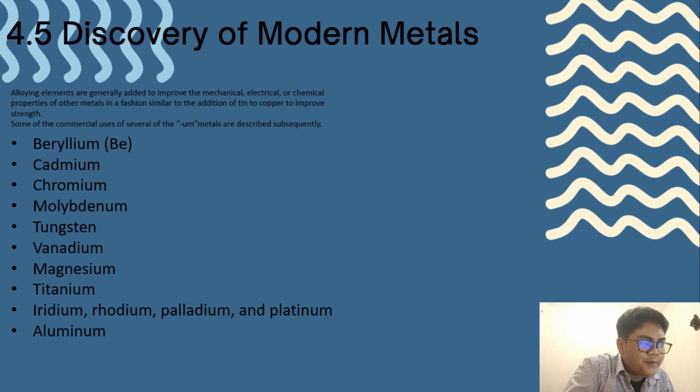Zinc addition to copper produces brasses. The copper beryllium alloys contain only a small amount of beryllium, approximately only 2%, but can be processed or heat treated to be much stronger than any low tin brass or copper zinc alloy. These very high strength copper alloys are used for the production of springs in the electrical industry and make non-sparking tools for use in potentially explosive atmospheres.